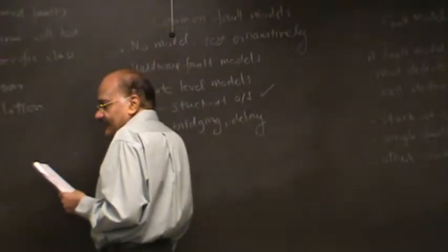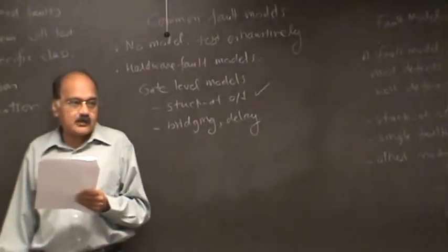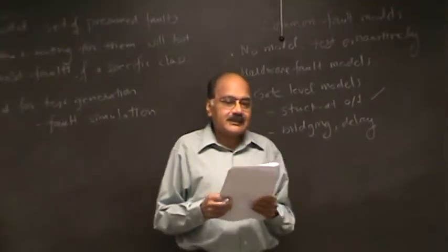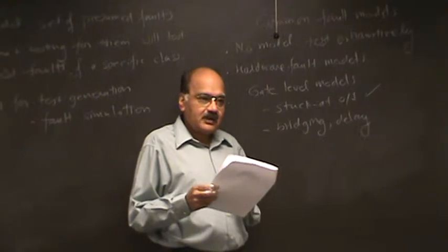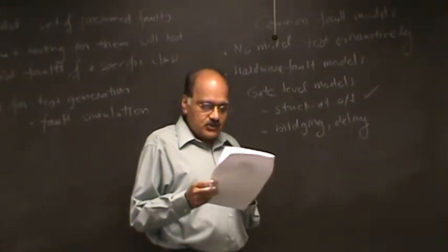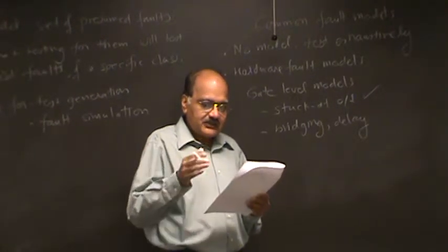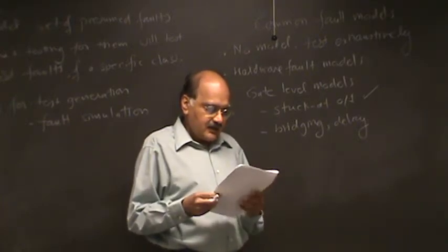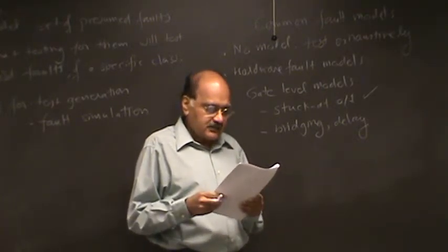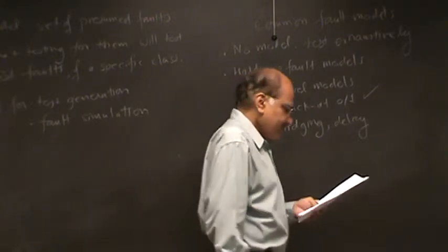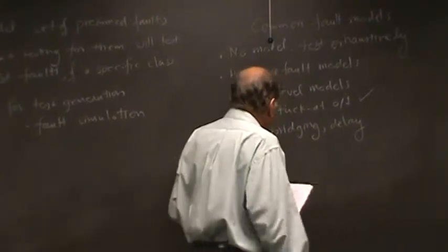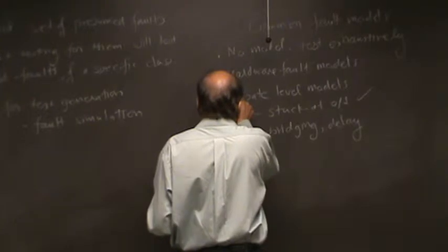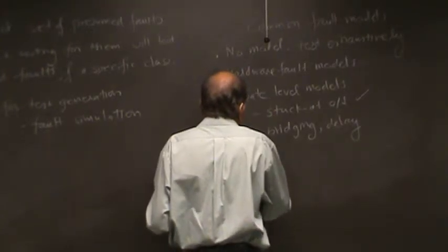Delay faults are actually quite important for hardware, because delays cannot be precisely controlled in hardware. So delay faults are quite common, and testing for timing related defects is a very important challenge. And you have then transistor level fault models.